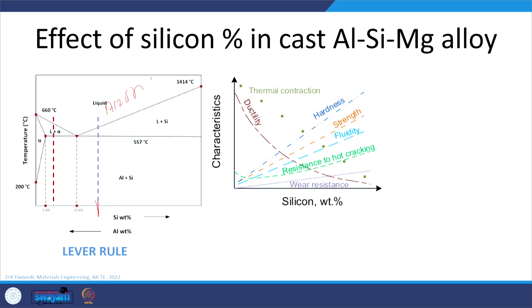So, this is the alloy composition corresponding to 20%. Here, on this side we have the eutectic and on the other side the primary silicon. If we consider the phase transformation on cooling a hyper eutectic aluminum silicon alloy, what will it produce? Predominantly it will produce the eutectic silicon, corresponding to this length. Say this is A, B and C.